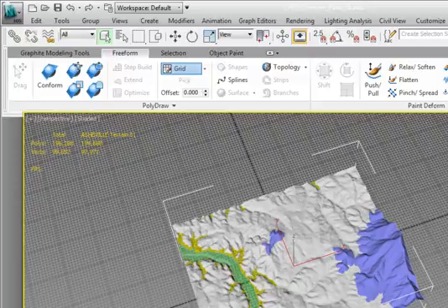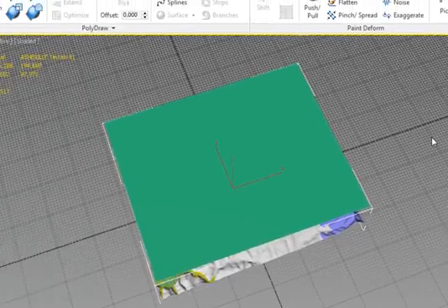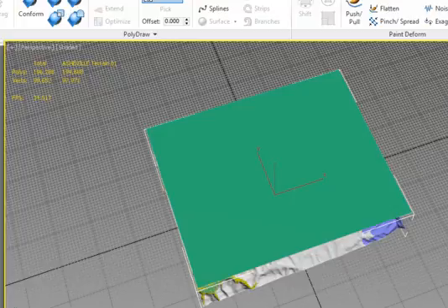194,688 faces. While this is not a tremendous number of faces, it far exceeds the 1,600 face limit we have for creating this terrain as part of a real-time application. In the viewport, right-click. From the Quad menu, in the upper right-hand quadrant, choose the Unhide All option. This unhides a simple planar rectangle that contains 1,600 faces, exactly the number we need for our low polygon model.